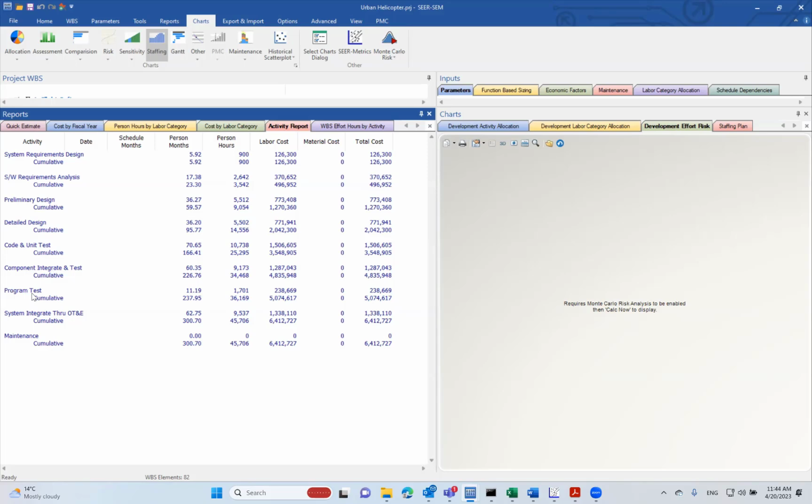Program testing is more like testing the software isolated, probably in a lab environment with stimulation, maybe an in-circuit debugger or simulators. And then we have system integration and testing. This is more like higher level testing where we test in the real hardware or a prototype, maybe an evaluation or a prototype version of the hardware.